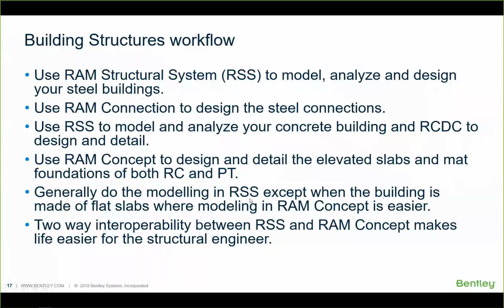We can proceed with the RAM structural system modeler. Or if the model is already done in a BIM program like Bentley OpenBuildings Designer or Autodesk Revit, we can import that directly into RAM structural system using the ISM workflow. I'll explain that ISM workflow later.